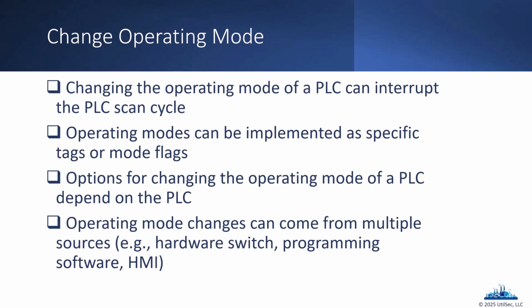And we can also think of the HMI, the HMI that controls and interacts with that PLC. It has the ability to make changes to the PLC. So we can look at hardware switches. We can use the official programming software from the vendor. Even an HMI we can use to interact with that PLC and determine what operational mode or operating mode it's in, and then potentially use that route also to take it out of run mode.